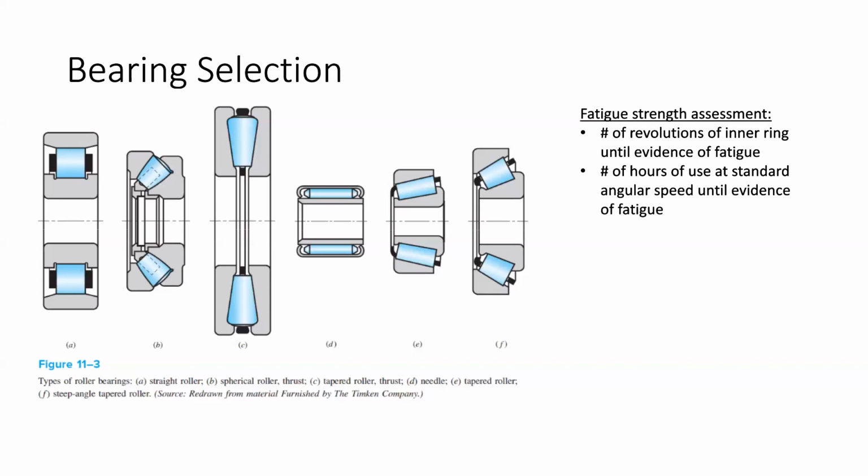So depending on the type of contact that you have between the roller element and the shells, you can get different amounts of pressure on the roller elements. And because this pressure is different, it actually manifests as different stiffnesses in the bearings.